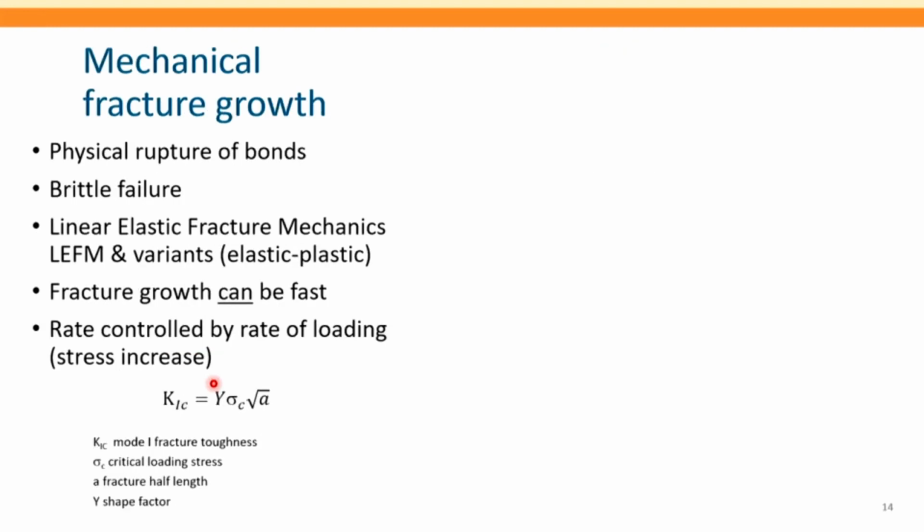Okay, so getting back to my lecture as a grad student. That's what I learned there. Basically linear elastic fracture mechanics, and it's summed up by this equation here. There is a material parameter. If you apply a stress to a material with an existing fracture of a certain length, and you exceed the load, then the fracture will propagate. It does not tell you how fast it propagates, just tells you it will propagate, right? And that's purely mechanical, okay? Brittle failure. The variance to this could be not just elastic, it could be elastic plastic, viscoelastic, whatever, but it comes down to the same thing.